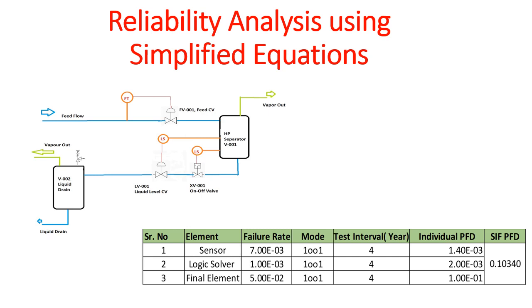In our previous lectures, we have discussed hazards. We identify the hazards. Then for more quantitative risk identification, we have done LOPA. From LOPA, the SRS got generated, and based on the SRS, we designed our SIF.